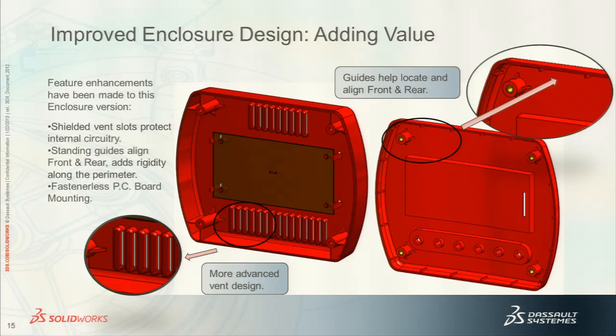I worked several years for a company named Life Fitness. They manufacture high-end exercise equipment. And when in a health club, if you go around with spray cleaners cleaning off the equipment, we were ending up getting shorts on the circuit boards because of liquids coming in. So rather than a straight access slot, we went to a more protected design here. So that's an enhancement, and it doesn't really cost that much to burn that into the tool.